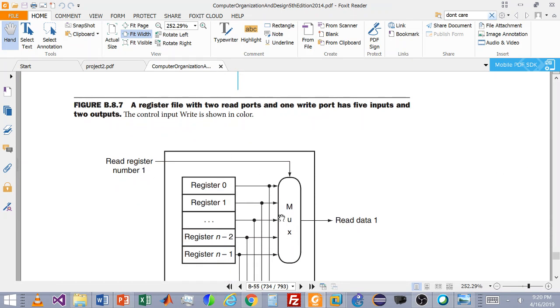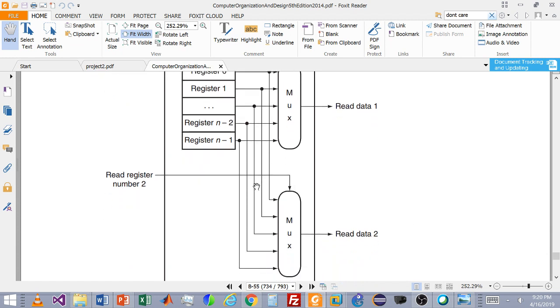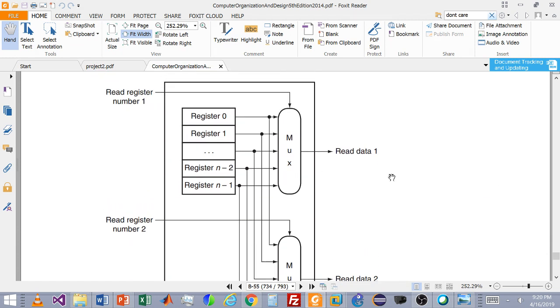And then we can use some combinational logic or a decoder as a mux to determine which to read out of this, because all we have to send in is the address of the flip-flop we're interested in, the memory location, okay? And then we also have to send in a clock cycle. When we send in these two things, what comes out is the read data. So that's how we build the logic for a register file for the read portion.